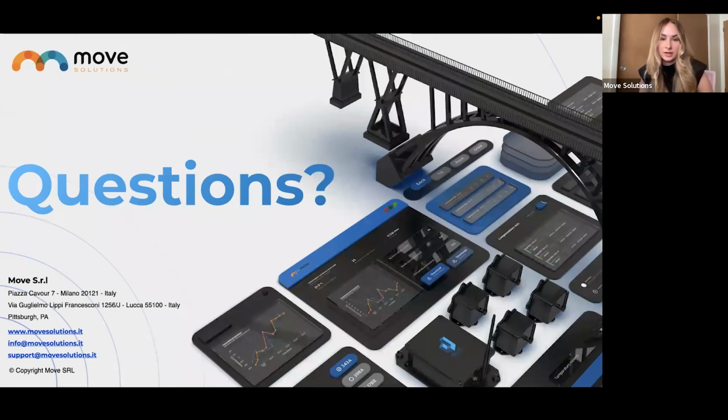For your construction vibration monitoring, do your performance specifications meet the requirements for USBM criteria for detection of building damage? Yes, so we work with the RI 8507 standard in North America, and we do not work to the ISEE standard, but that's for drilling and blasting. We work to the standard for building damage. So it's the RI 8507 standard.